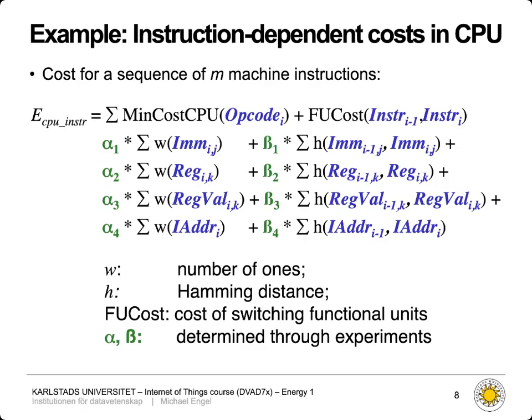And these alpha and beta are what was actually determined by executing specifically prepared amounts of code on this ARM7 platform here, and then measuring the respective power consumption to, in turn, backwards derive all these parameters that make up our model. Of course, these parameters are only valid for this specific chip. So if we use another ARM7 TDMI, which might have another internal circuit, then we'd have to do all the measurements over again, because this chip might have different ways to, for example, do additions.